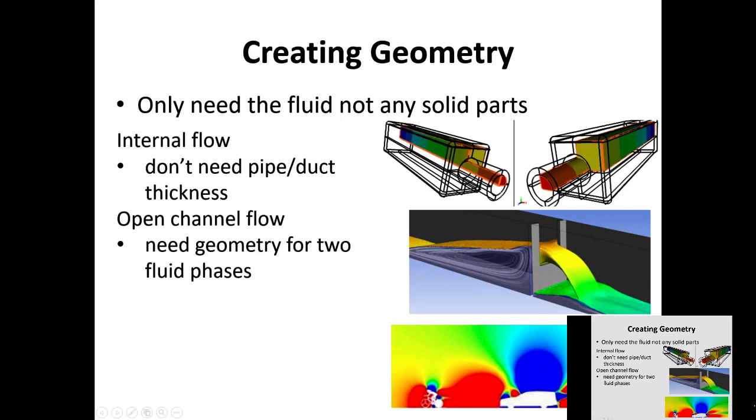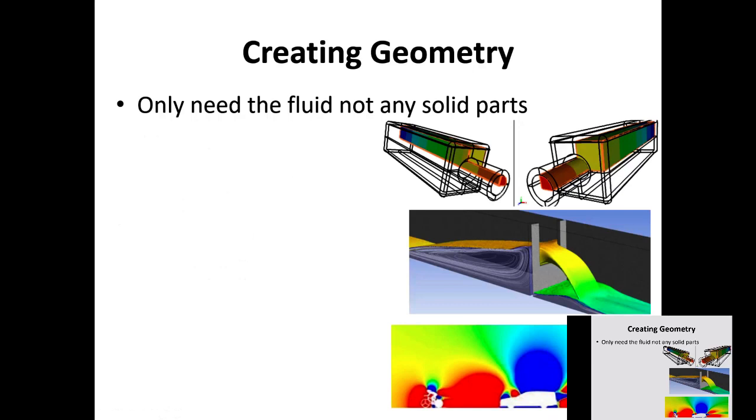So remember, when you do a flow calculation in CFD, you only look at the fluid, not the boundaries. Well, not the container or the element that is containing the fluid. You are only looking at the shape of it. You are not looking at the material or material properties of it, apart from if there is any heat transfer.